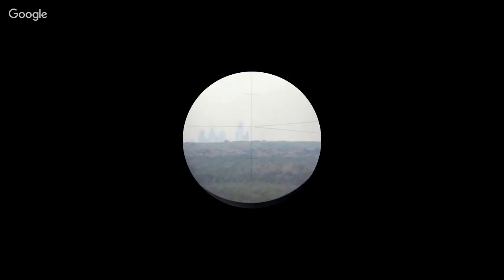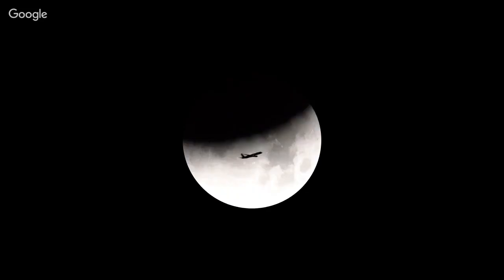The mass center of the Earth is the origin of that reference frame, or that coordinate system. It's 0X, 0Y, 0Z meters. It's in meters. And as these satellites fall around the Earth in their orbit, those coordinates of those satellites can be computed at any instant in time. This whole thing depends on timing and being able to track those signals to intersect those ranges. So, like at some instant in time, that satellite has an XYZ coordinate.